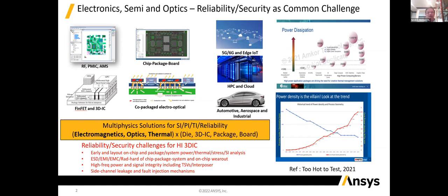In the second area, for HPC and cloud applications, with a lot of GPU and CPU design, the power demand is continuing to increase. We can see 300 watts, 500 watts, or even 1,000 watts and more. Therefore, the power density continues to increase. Given 10 microns by 10 microns, it goes beyond 5 milliwatts, or can reach 10 milliwatts in certain designs or testing scenarios.